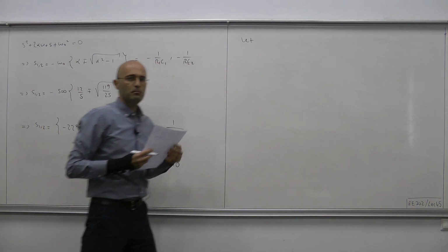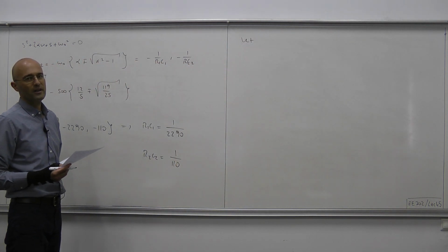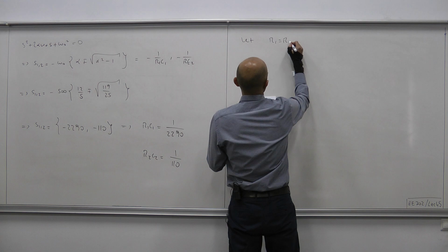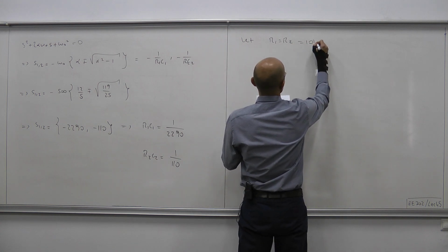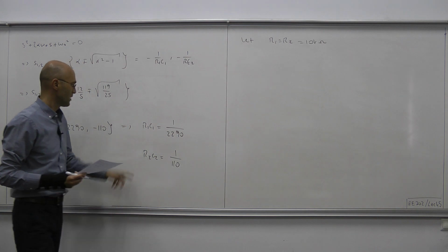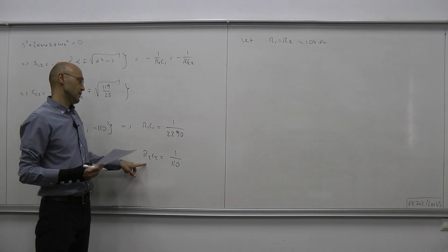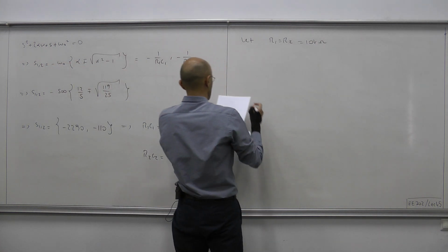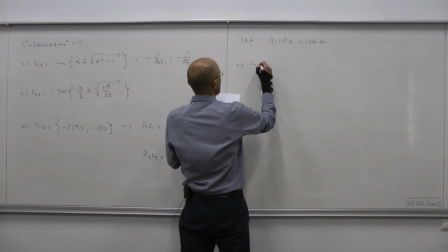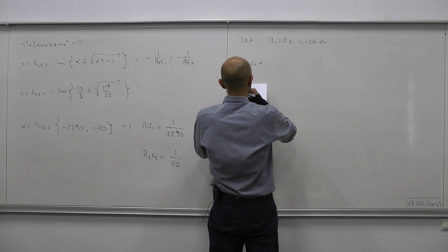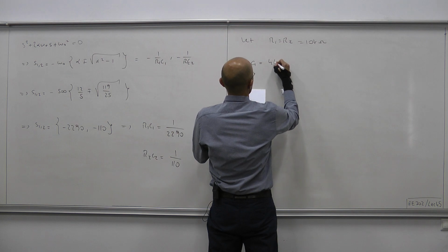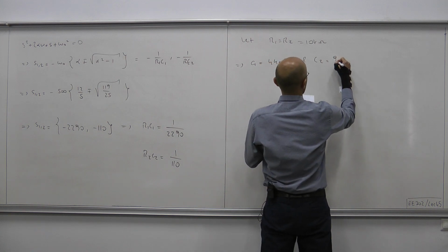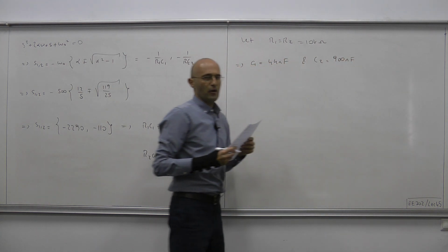We were told to choose the resistance values not smaller than 1 kilo ohm, so let us choose them both at 10 kilo ohms. So R1 and R2 are now chosen, and from which we can obtain C1 and C2. That produces C1 equals 44 nanofarad, and C2 equals about 900 nanofarad.